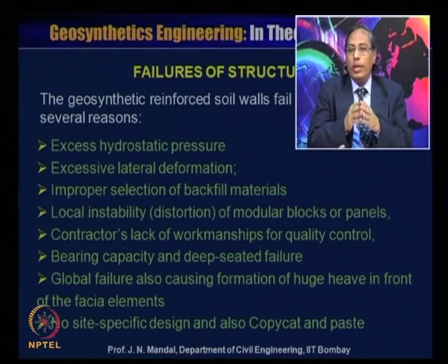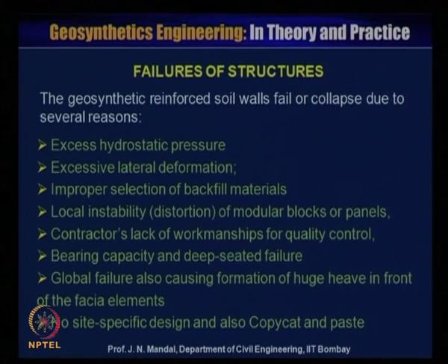This quality control is very, very important. It requires proper testing, proper compaction, and proper moisture content: what moisture content is to be added, how you compact, and whether it will achieve the required compaction or not.